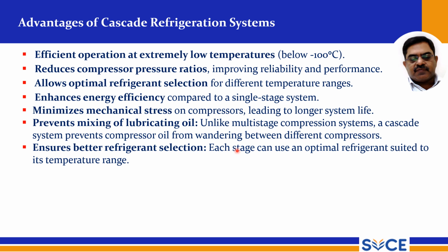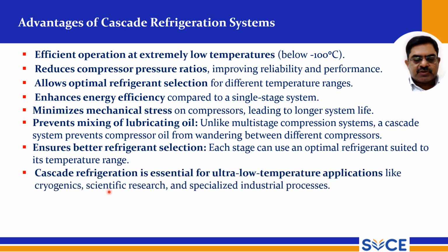It ensures better refrigerant selection, where each stage can use an optimal refrigerant suited to its temperature range. So depending on the temperature range, we have flexibility to use different refrigerants. Cascade refrigeration is essential in ultra low temperature applications like cryogenics, scientific research, and specialized industrial processes.